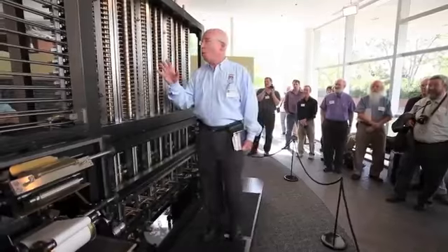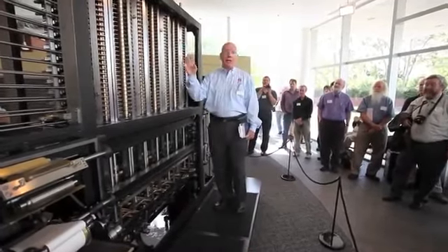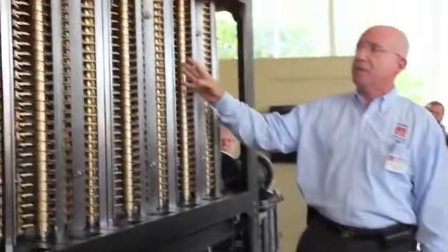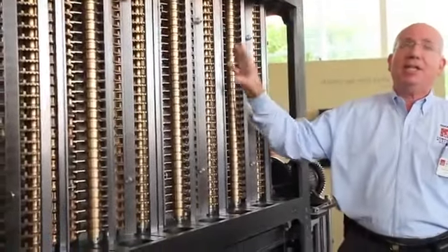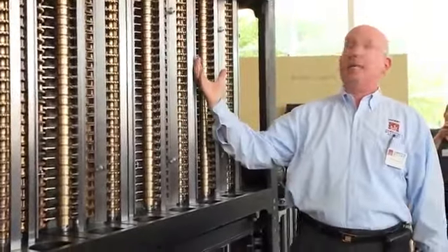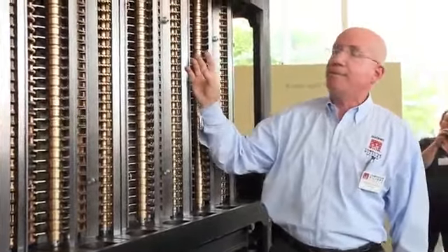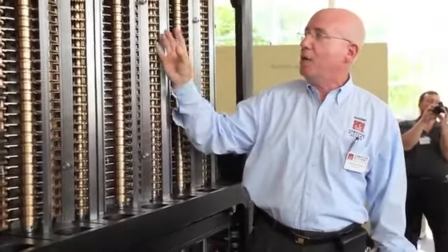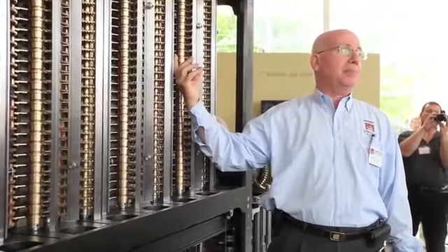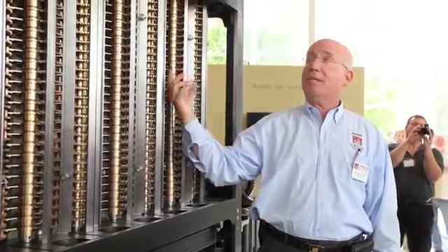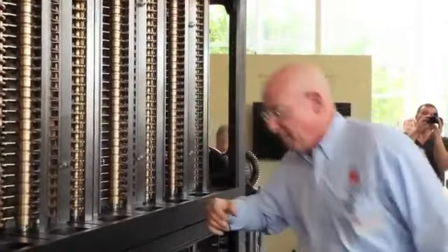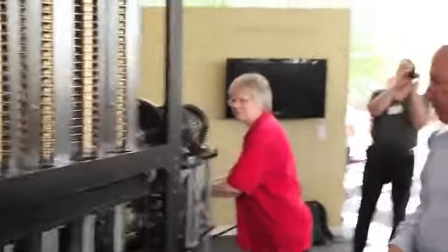Let's crank it. I want you to watch as the addition takes place. We've got this equation set up, so in fact, we're using 5 of the 7 difference columns. And you will see the addition taking place by these big sector gears in between, adding the numbers from one column by rotating them back towards 0 value, transferring their value to the next column, and then resetting the column to its original value as it comes down. And for that reason, these columns jump up and down. Go ahead, Julie.